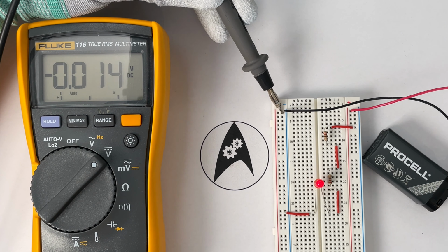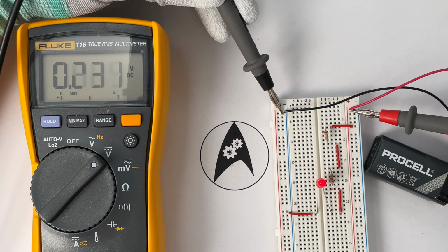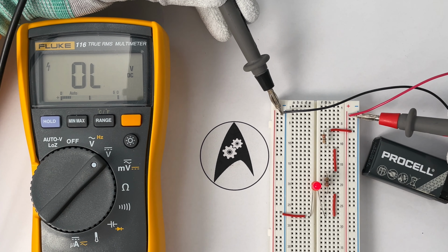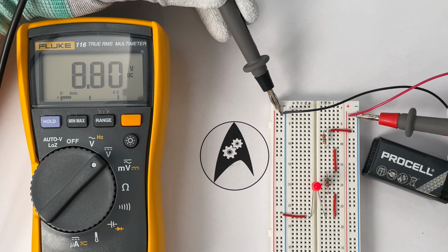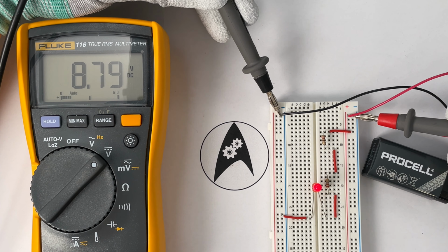Now, if I start from the positive connector, you can see in the display of the voltmeter that the voltage which is provided by the battery is at 8.8 volts, which is roughly according to the specification, which says 9 volts, but it's a used battery, so maybe there's already some charge drained from the battery. So this is the full potential energy, the full potential which I am measuring now when I hold these tips directly against the terminals of the battery.